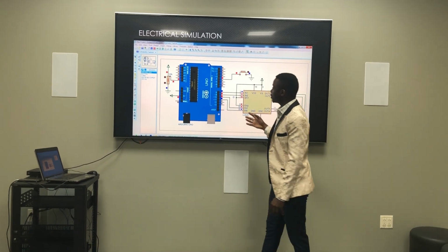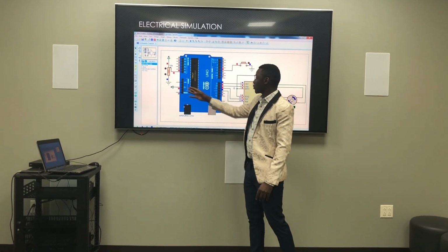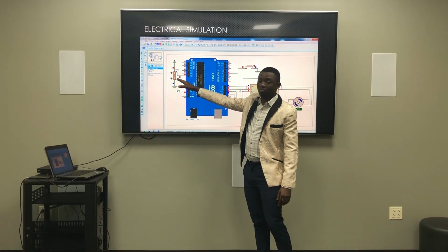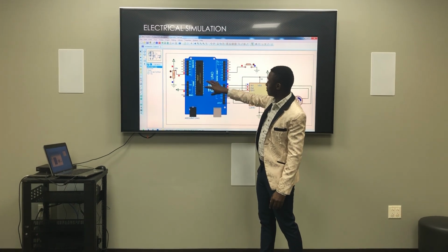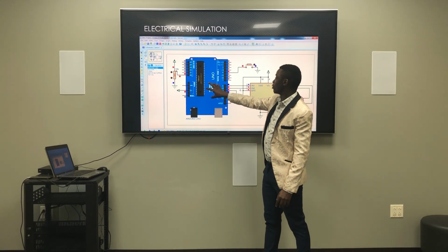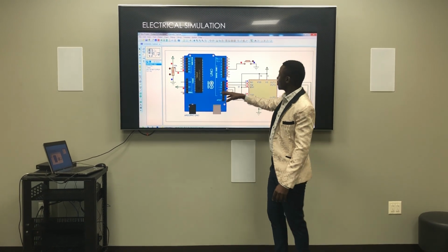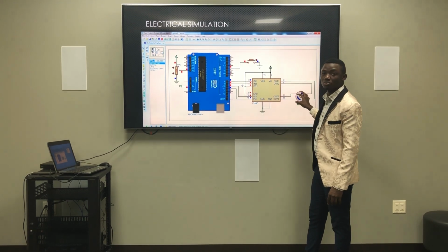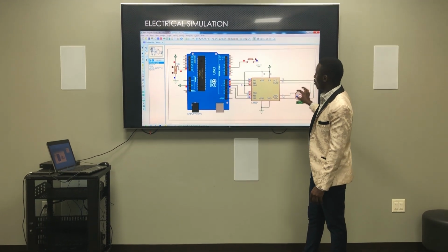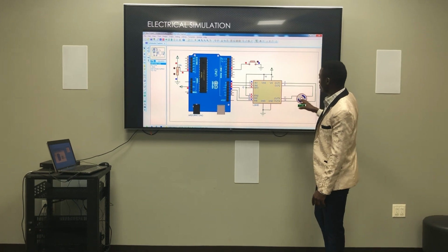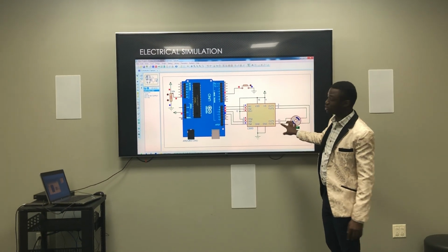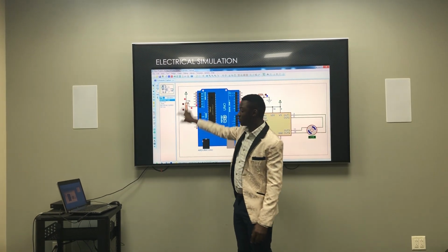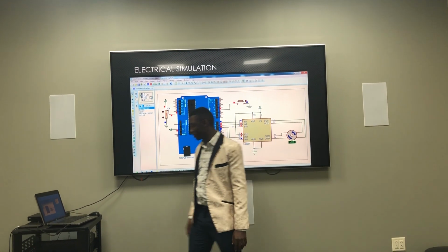When we open the chute, we're going to have a reading on the potentiometer, use that reading from the potentiometer and decide using the controller, which is the Arduino Uno. Then the result of that is going to determine whether we are going to be opening the motor or not. So basically, that's it. The motor representing the chute, the Arduino representing the PLC, and the potentiometer representing the weightometer, which is the analog signal.